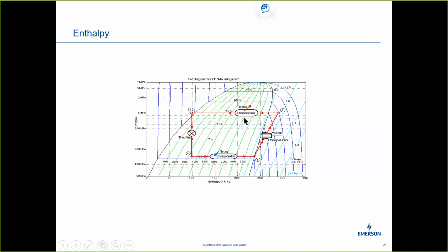First of all, between these 2 lines of the dome, that's our 2-phase area, okay? Outside the dome, this is liquid and this is vapor. Everything inside here is in a real simple form. What this line is telling you, the pictures are actually here for you on this one. I picked this out specifically, but a lot of times they're not. This is what the compressor's doing. This line is telling you what the compressor's doing, whether it's by the pressures over here or the temperatures. When it comes across here in this area, that's significant. That's showing you the condenser, okay? And this says condenser, that's why I chose it. But if you ever get into a situation where you're working around engineers or designers or your service manager and you want to be in that conversation, that's what this is telling you.